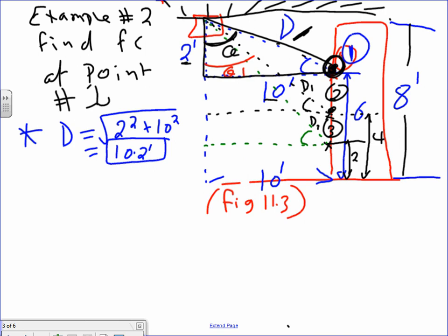That's the first step that you need to do. Find the distance. Any comments, guys? Any questions about finding the distance? Why do we care about finding the distance? Because I need to plug it into the formula that says candela power sine Q over distance.